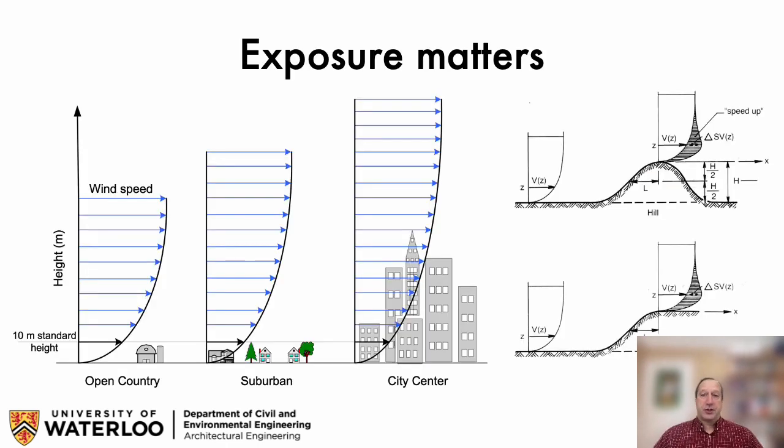Now, before we drill down into the actual building or even the particular narrow site definition, the location on the planet depends. That's a climatic effect. And then we move to exposure. And that means, is it a tall building in a city? Is it a short building in the country? Or is it a tall building in the country? The wind speed directly relates to rain deposition, but not just your average wind speed. It is the local wind speed.